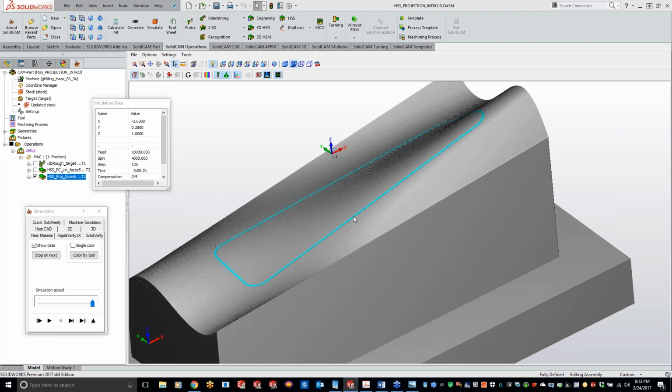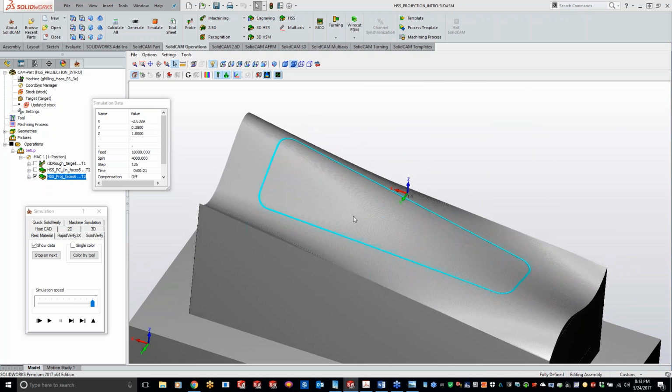And where this kind of comes in handy is I had a customer that wanted to do knurl on his part on a really contoured 3D surface. So he grabbed all those lines, and then we were able to create knurl on a completely 3D surface, which was done fairly easily just by grabbing those sketches. One nice feature about that is it saves you the work of having to project that sketch inside SolidWorks, and we can let SolidCAM take care of the projection of it.